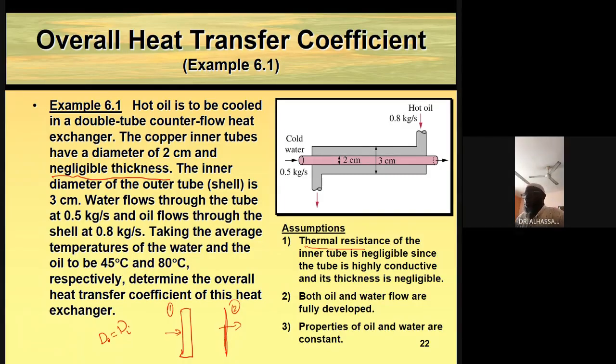You understand me? But the convection comes into it when you are talking about the engineering design. You want to calculate maybe the amount of heat transfer. You want to look at the thermal resistance, the concept by which the heat is being transferred from the hot fluid to the cold fluid.